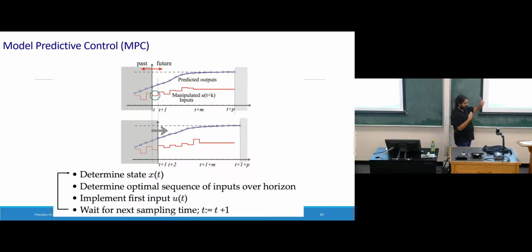So you can compute chess moves maybe 10 steps ahead, thinking about what my opponent will play if I play this, if I play that. But at the end of the day, you have to only make one move and then wait for the opponent or the environment to react back. That's sort of what MPC is doing, right? So if you see this picture, we compute this optimal sequence, but we only input this control input to the actual system. So at t plus 1, we have made our choice.